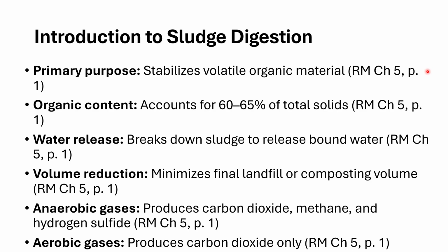And recall that in the primary clarifier, we have a scum skimmer up on top of the water surface, and that's going to scrape and guide that scum into our scum box. And we're going to take that away so that we don't send it off to future treatment. And that sludge blanket forming at the bottom of our clarifier, we're using a rake apparatus to send that to the center of our primary clarifier, and we're going to waste some of that sludge. Well, that wasted sludge from the primary clarifier is going to go to the digester.